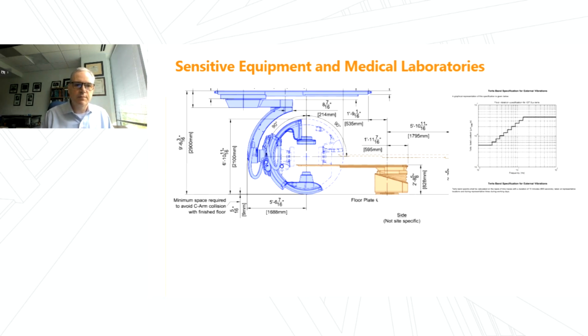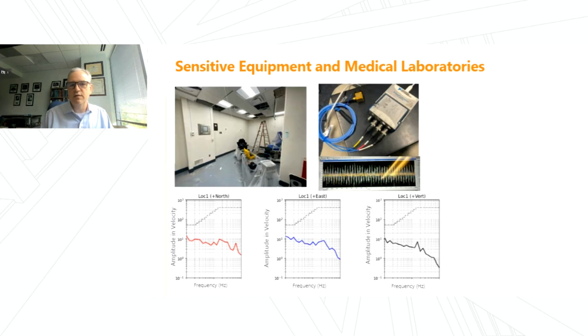This is the biggest concern in these environments. It isn't the building swaying or things like that, but rather footfall traffic, operations near the unit, as well as mechanical systems. To address this, there is a fairly simple setup for testing. Basically, a laptop and a simple mobile accelerometer array allow us to make those types of measurements.